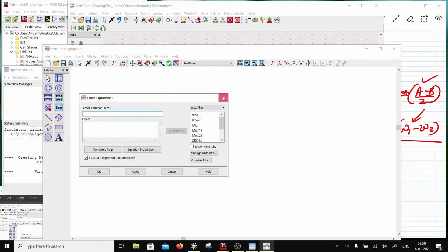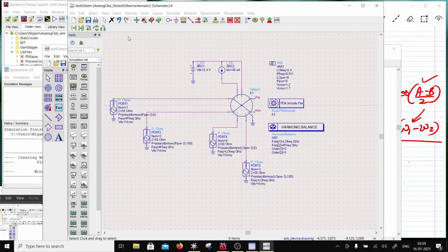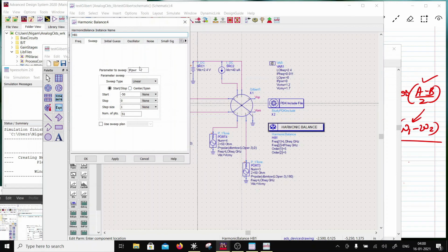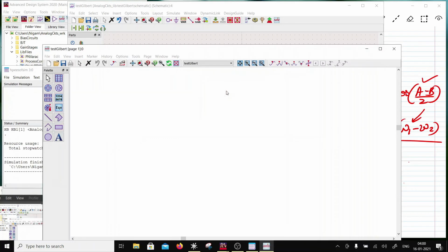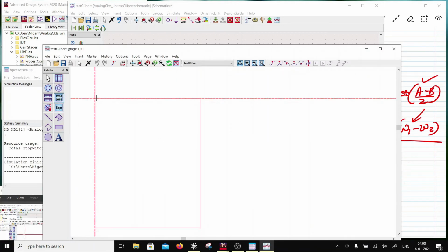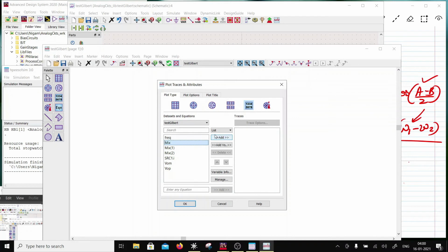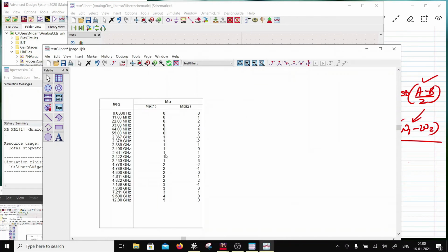First of all, you should know which is the output. So in this case, I will switch off the sweep. I'm not going to sweep this one. Let's look at the mix at a single power level. When you hit simulate, you are going to have something called a mix table. We are looking at mix components, basically the up conversion, which is 1 and 1.